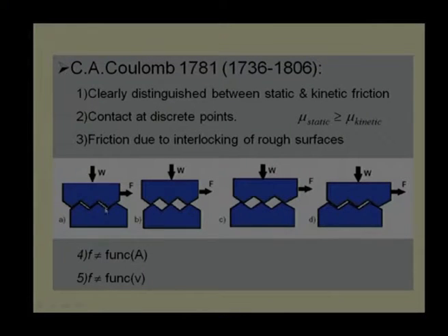He gave a couple of examples. There is a roughness profile of one surface, and the roughness profile of the other surface is more like a sawtooth profile. When the normal load is applied and the friction force is trying to push it up, Coulomb thought that maybe without any deformation it starts gliding up, as it requires a force to move the component out of the pit, and that is the friction force. However, later it was realized that when it is going down, the same energy will be gained back, so there should not be any friction force. Some explanation was given that there are always hysteresis losses. When material is moved from one place to another, we will not necessarily get 100% of the energy back. Some energy will be lost, and that is going to give us the coefficient of friction, or a friction loss.